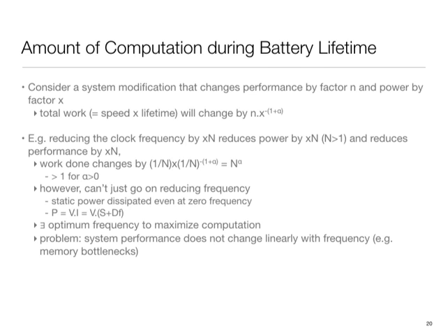However, I cannot keep reducing the frequency because other effects come into play. In the extreme, when I go very low, the leakage energy of the system will begin to dominate. And battery leakage will also become a factor. So you cannot just keep running slower and slower. If you take those static effects into account, there would be some optimum frequency at which you should operate the system, which rightly balances what the processor is doing and what the battery is doing. So there are non-idealities on both sides: the role of static power on the processor side, and static leakage and this non-ideality on the battery side.